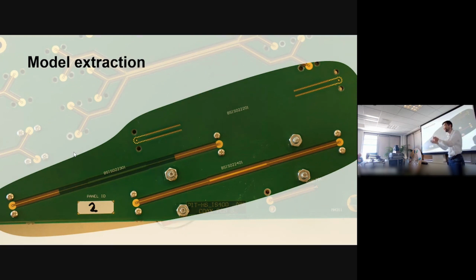So they use the kind of measurement technique that gives you a consistent result, but not necessarily useful or good enough for electromagnetic simulations. So to see to what extent it was a real problem, we put, thank you, Nick, this BT structures on our test PCB. So it's just 50 ohm trace with a slightly thicker trace and then 50 ohms again.